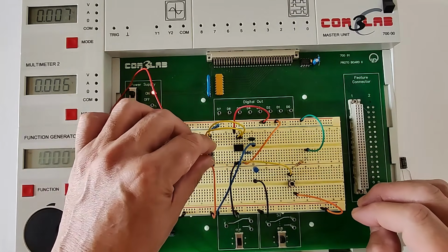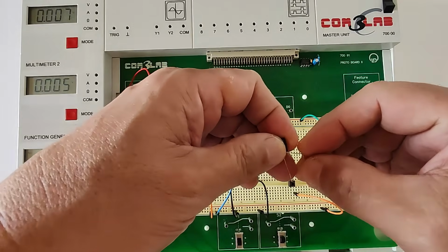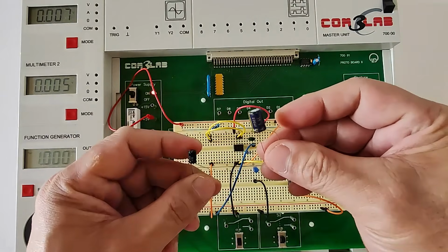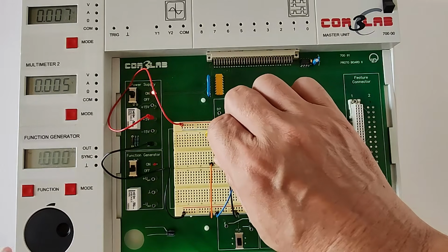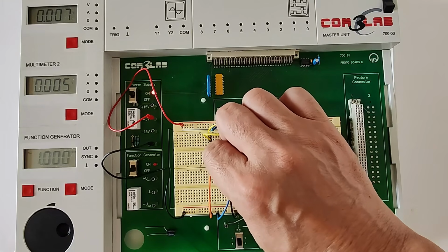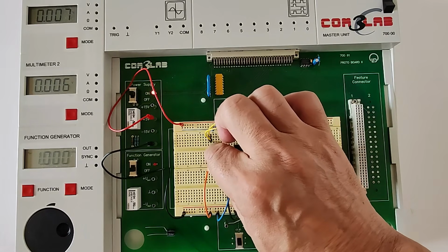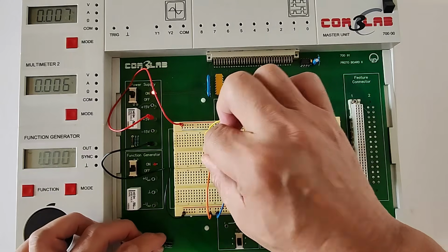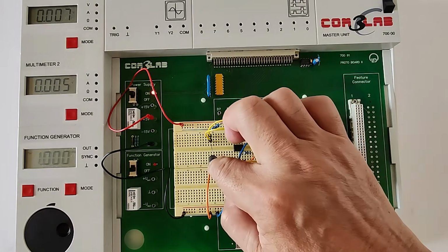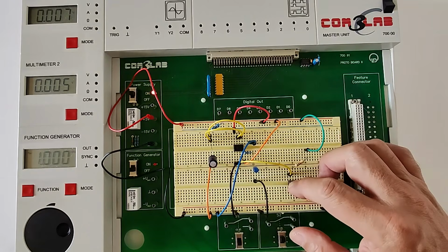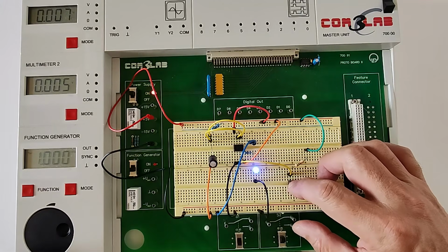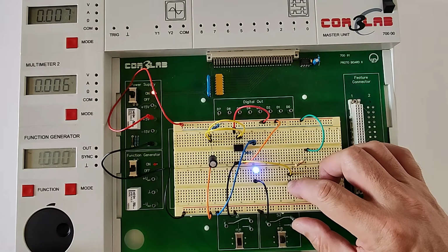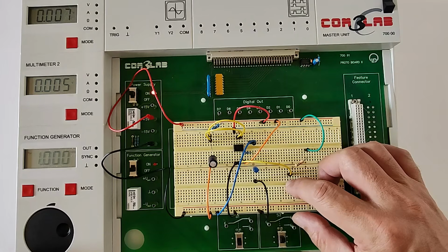Okay, so if I again change the 100 microfarad capacitor, this one, with an even higher value capacitor, like what I have here, a 220 microfarad capacitor, we can expect now the blue LED to turn on longer before it switches off automatically. Let's do that now. Okay, there. So I have a 220 microfarad capacitor here right now. Let's observe the blue LED that we have here, okay? See, it's longer. See? That's almost 3 seconds. It's on. See?